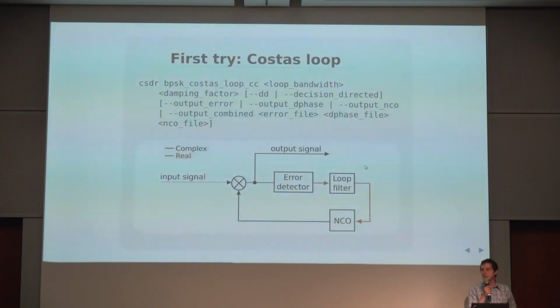And my first try was a Costas loop on this problem. However, if the user clicked just a few pixels away on the BPSK31 signal on the UI, where you can select on a waterfall diagram, it can cause around 40–50% of frequency difference compared to the signal bandwidth. So that's a problem. I had to increase the loop bandwidth so much that it worsens the tracking variance, and it didn't work as I expected.